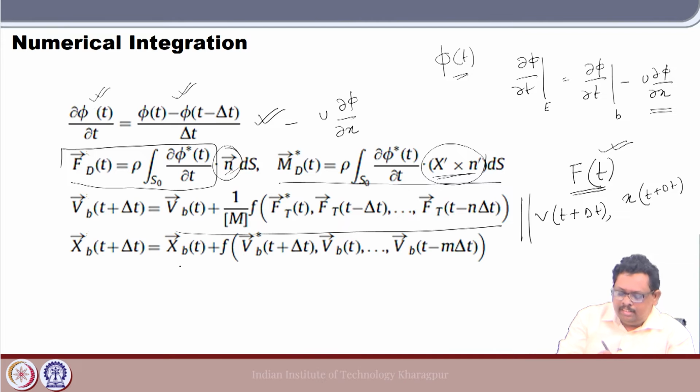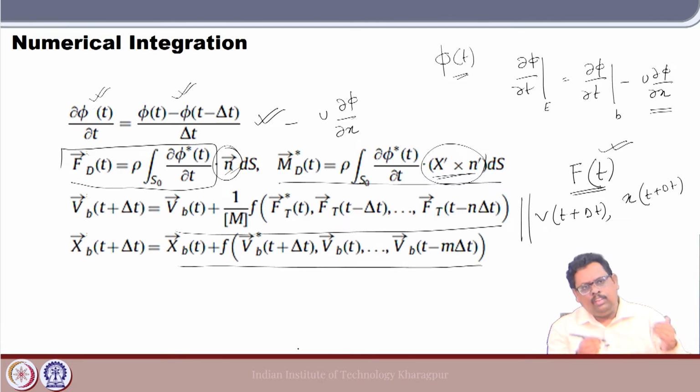I do not mention here any particular scheme, because there are many. If you ask me what to use, I prefer to make delta t small and use the Euler scheme, which is what we used when we wrote the impulse response function code. It is pretty robust if you make delta t a little bit smaller.